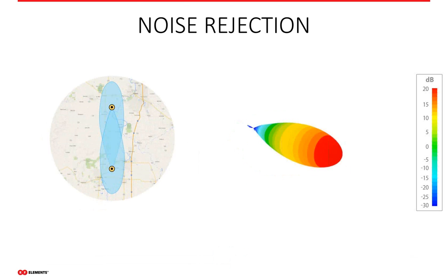If we look at the same type of high gain horn antenna here, again, you see practically zero side lobes. So all you have is that main lobe. That's the key point to major isolation with a horn antenna compared to other point-to-point antenna technologies.